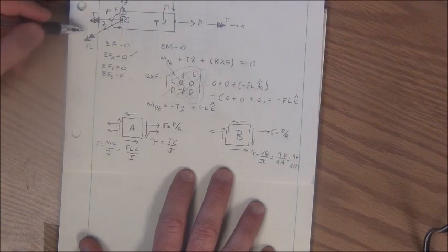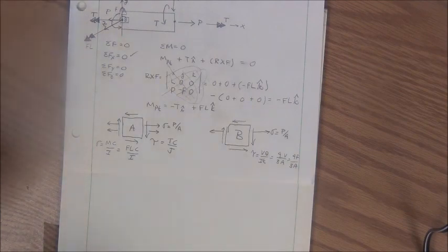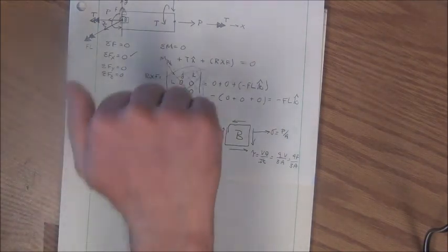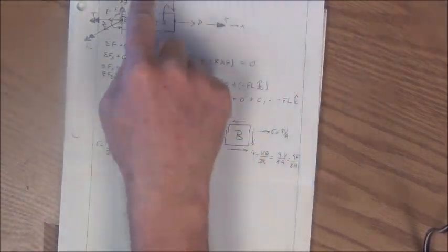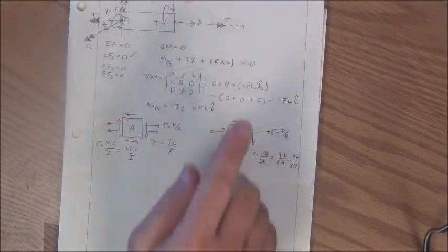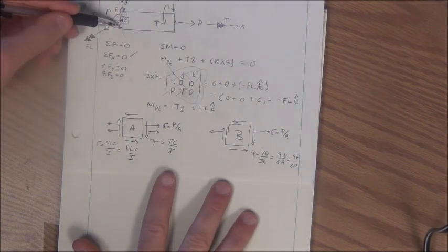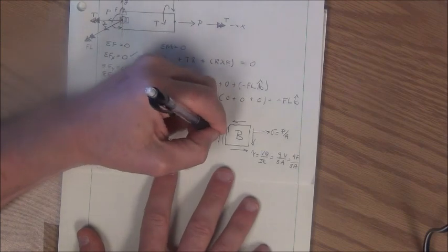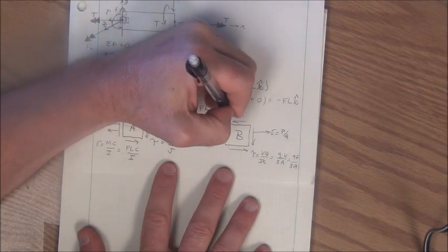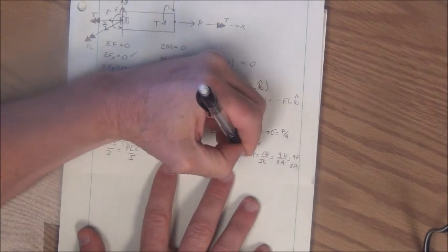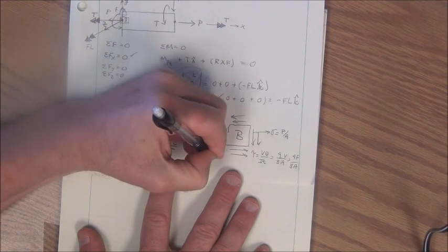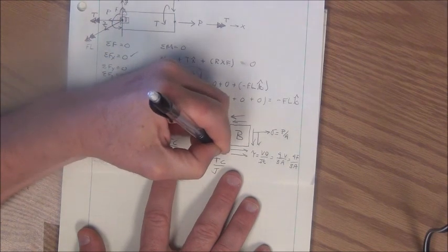We've now considered the 2 point loads in my geometry, and we're ready to look at the torque and the bending moment. The torque, again, is going to try to twist B. It's twisting the shaft, so we know that it's not a moment, but that it is a torque. And again, on the cut face, it's going to twist that up. So on the cut face, we'll be going up in the same direction, and we have a tau is equal to TC over J.